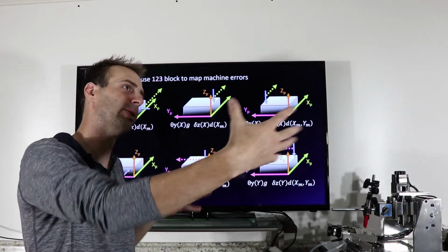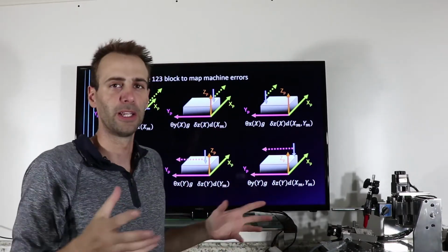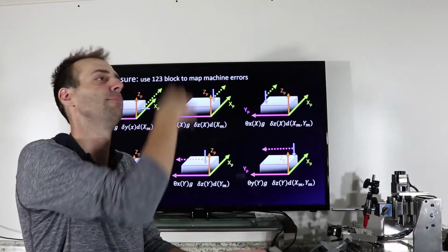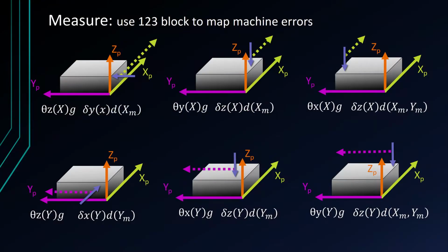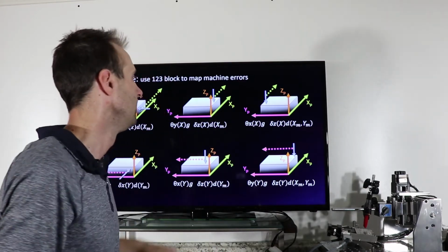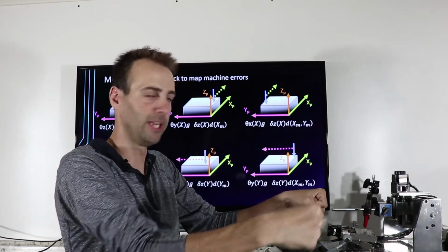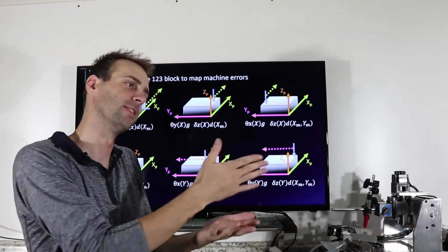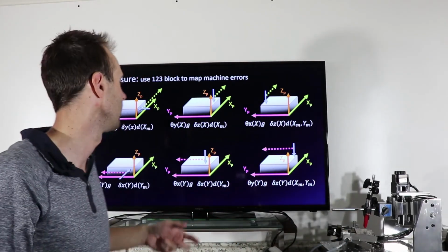Okay, so this is where you start building that 3D map, and then maybe do this 10 times. I don't know if I would really recommend that, especially not at first. Kind of come back to this one. But in the end, this one's not enough to give you information about roll around x as you move x. You have to offset your indicator to catch that geometric error around x, okay? And then your dynamic errors, again, if your table twists and is also bent, you need this to decouple that. You need to do several to pick up that bend along y with the twist along x, okay?